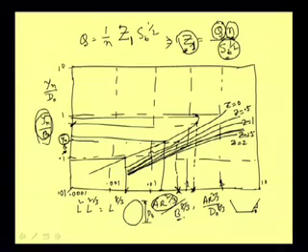It will no more be open channel flow, and rather it will become a pipe flow concept, and then we will have to think about other theories and relations. That is another issue. But here, till it is open channel flow, not completely covered, we can have 2 normal depths.